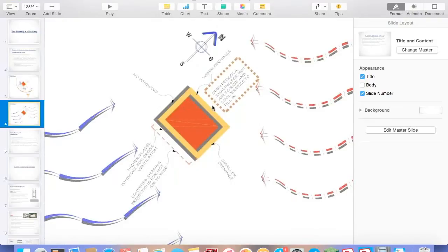All of us know that hot air rises, and so we can manage our windows in a way that we have wider openings on the northern side and smaller openings at the upper level on the south side. So what will happen is the draft will come in from the north side and then it becomes hot and then it will try to rise from the south windows, which are placed at upper level but shaded properly.